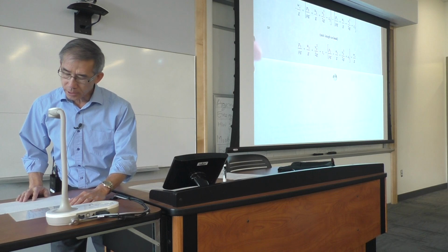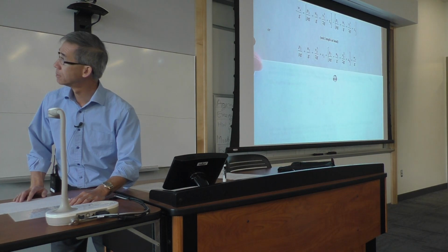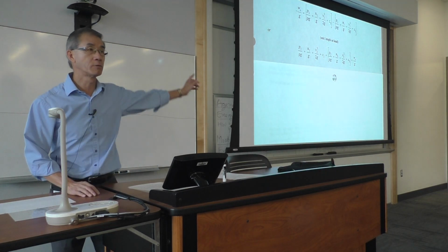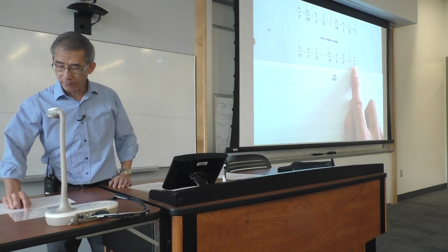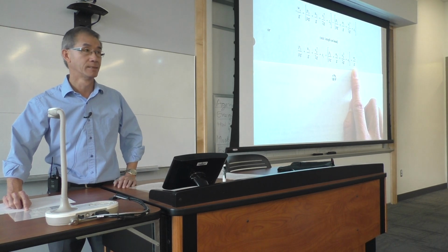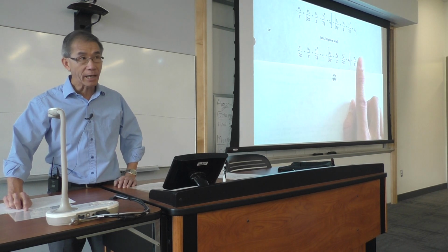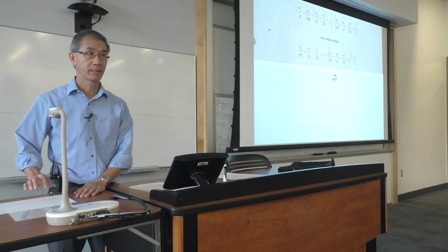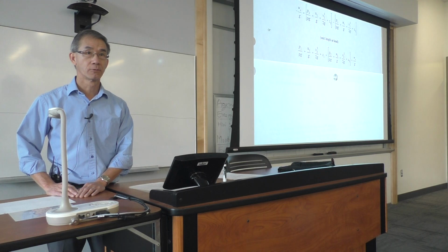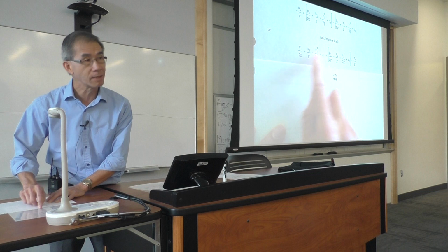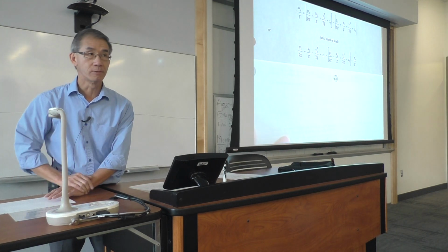So now you see how this equation comes about, which we finally put in a form that is similar to the energy equation behind the screen. I have now this Ws over g. So this is what we call H sub S, S stands for shaft. What I don't have is, where is the H sub F? Can you make a guess? Where is the H sub F? How do I get rid of U2 and U1, which don't appear in my energy equation?